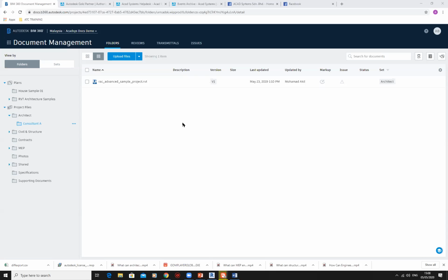So it's all created automatically from the Revit model. I didn't create anything in BIM360. It's all extracted, but as I said again, you have to work properly in the Revit model, in the leveling and so on. So modeling-wise, you have to work in detail on each level. You have to make it separable so that you can make it compartmented, like a compartment in BIM360. It's all automated. I didn't do anything to create the levels. It will automatically read the levels created from Revit.